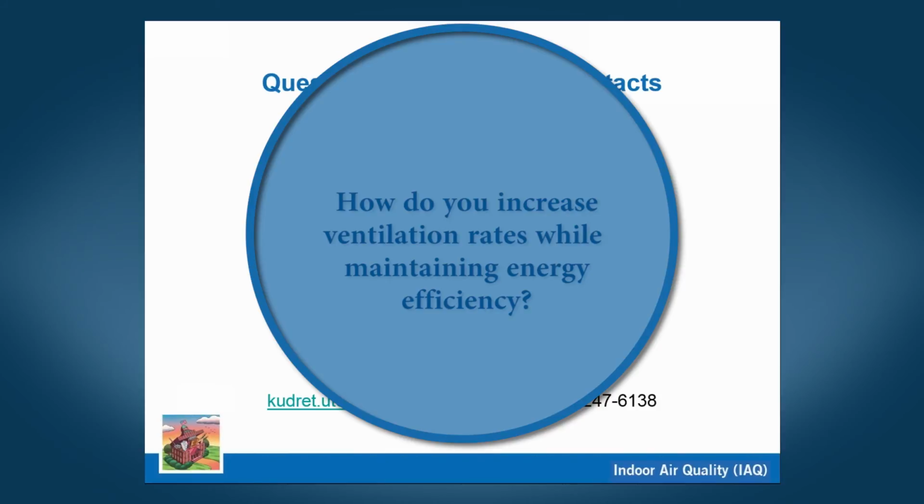A good point for people to remember is most of our buildings, most of your buildings, I hope, you can look back at whatever standards were in place at the time. We have a lot of newer schools, built to newer ASHRAE ventilation standards. So before simply increasing ventilation, look at the standards. What standard are you trying to meet? Make sure that you're not already ventilating more than you need to.